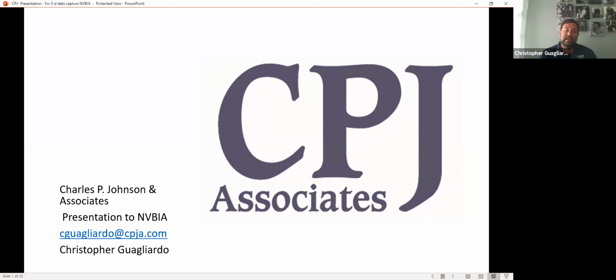3D scanning, I'll take you through this. It's going to be a nice introduction, showing you the different aspects that you can do with it. There are many different things you can do with scanning. And the way these robotic transits are being produced, you can now have a total station that also scans. So if you have crews out there shooting topo or anything else, and you're afraid they missed something, you can just have them do a scan at the same time, and you just pick up extra data.